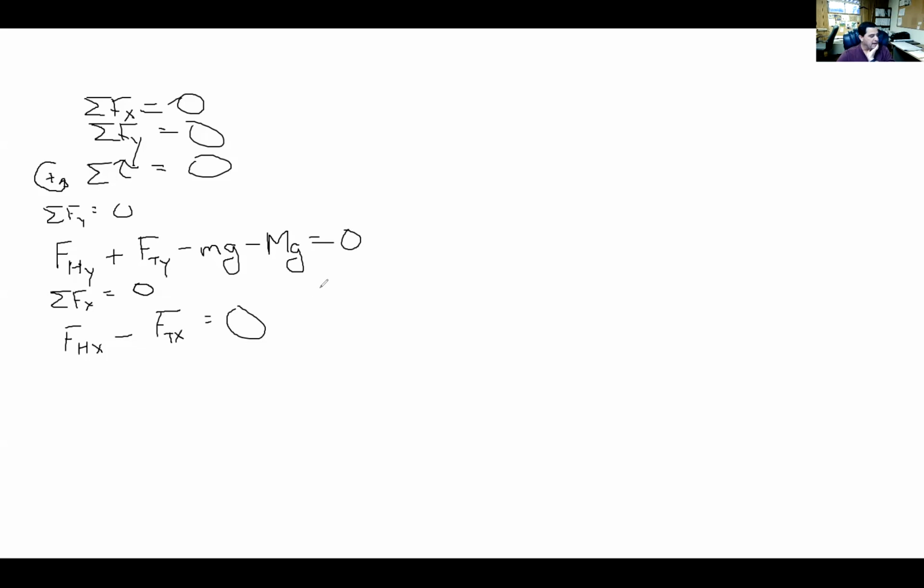So what we need to get us started is to sum torques. And like I said, I'm summing torques about the very end of the beam where the cable and the sign and the end of the beam all kind of intersect out at the far end of it.